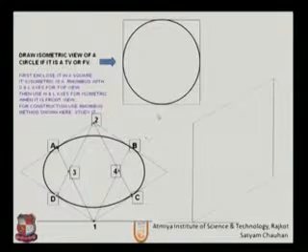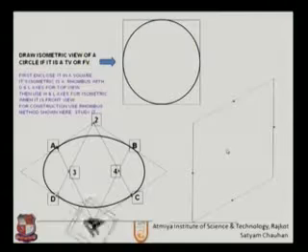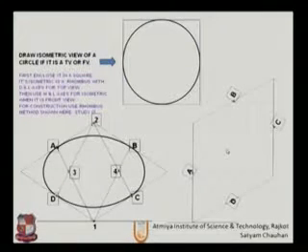Next, what will be the isometric front view of that circle? So draw a rhombus, as we have the square out of the circle. The same points, the same steps. We need to find the midpoints of all the lines. To find the midpoints, we know the measure of the square, so simply dividing by 2, we can identify the midpoints. Give the names A, B, C and D.